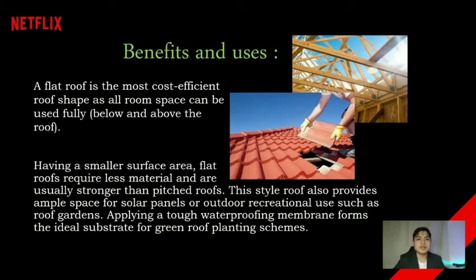Benefits and uses. A flat roof is the most cost-efficient roof shape, as all room space can be used fully below and above the roof. Having a smaller surface area, flat roofs require less material and are usually stronger than pitched roofs. This style of roof also provides ample space for solar panels or outdoor recreational use such as roof gardens. Applying a top waterproofing membrane forms the ideal substrate for green roof planting schemes.